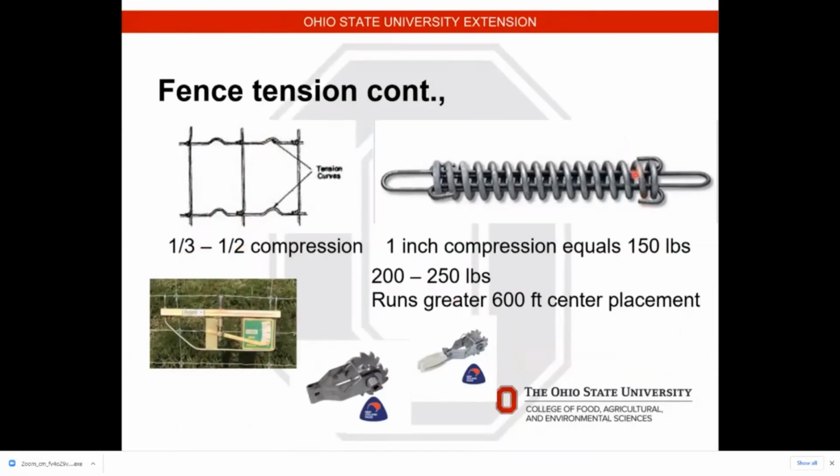These springs, if you tighten them an inch, they claim it's 150 pounds. I've seen some recommendations of 200 to 250 pounds of tension on high tensile. And boy, if you go that high, you better have good corner posts. That's a lot of tension, folks. 100 is probably where I would more likely stay.